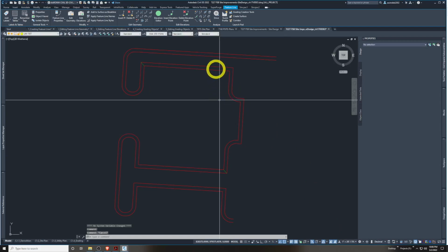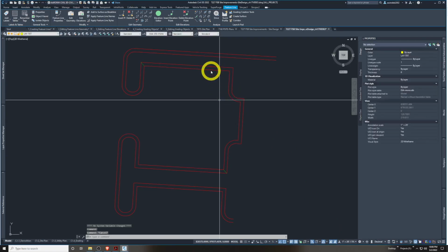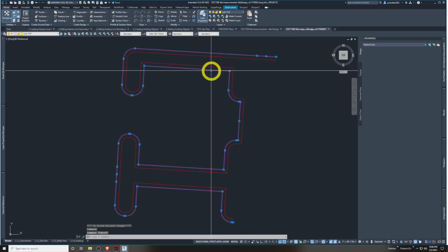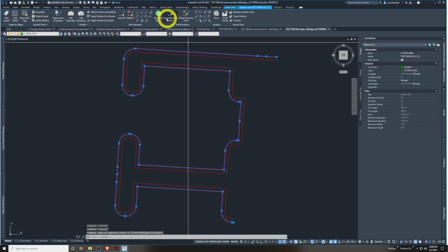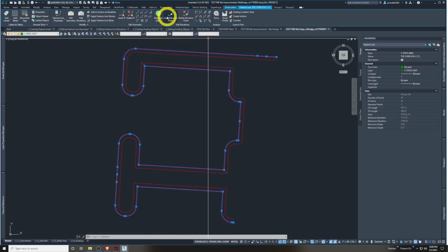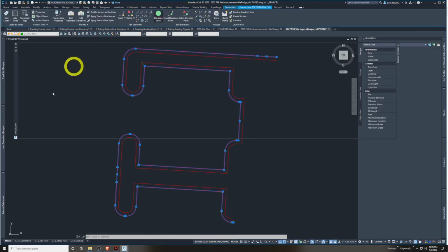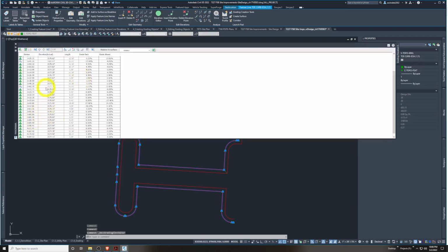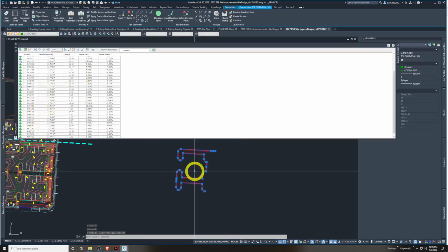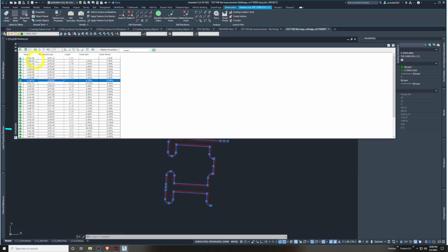So going into some of these tools, if I go to my feature lines here, this isn't built on a surface yet, but to quickly show these a lot more surgically, we have our horizontal stuff. Let's pretend that's all set. We're going into vertical. So we go to elevation editor. We have all of our elevations across this bad boy. And we can see our stations.